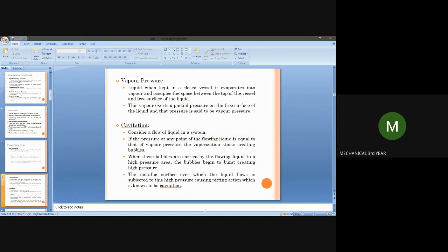Okay, so the releasing of air also creates some amount of partial pressure, and all put together, the maximum pressure is created on the area where the water is in direct contact with the metal, I mean the pouring point. Okay, in that pouring point, a small pit is created. A pit is a small dent, and that dent is said to be the cavitation. Okay, hope you all understand, right?